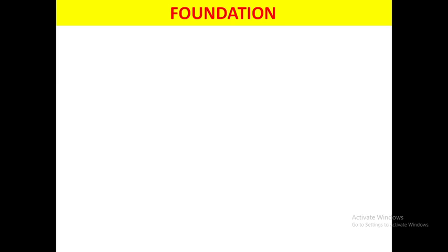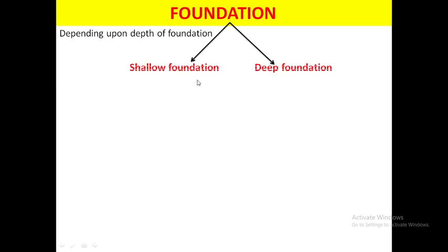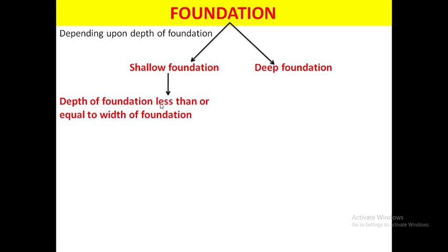Depending upon the depth of foundation, it is classified into two: shallow foundation and deep foundation. If the depth of foundation is less than or equal to the width of foundation, then the foundation is known as shallow foundation. When the depth is more than the width, it is known as deep foundation.